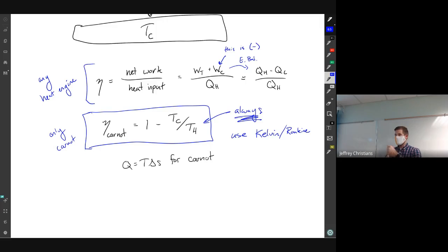make sure we're using Rankine. Rankine is the English unit equivalent of Kelvin, where 0 is absolute 0, but a degree is the same size. So, right, 0 Fahrenheit is negative 459 something. I think, I don't know, I'm better at the Celsius one. I think 0 Kelvin, absolute 0, is negative 459 Fahrenheit. So that's 0 Rankine, and 0 degrees Fahrenheit is like 459 Rankine, but 1 degree is the same size.